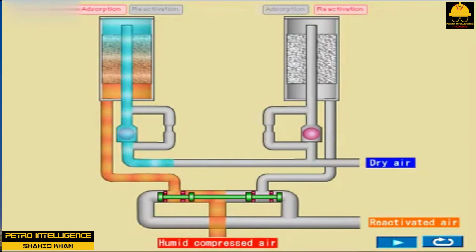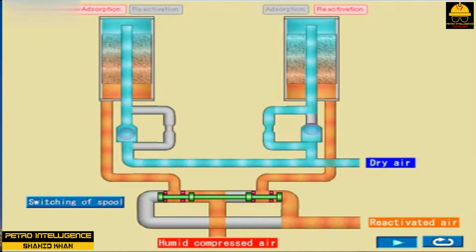In the case of a final product, the quantities are usually so large that special equipment is used to handle it, but the principle is the same. The moisture adhering to the solid is vaporized and carried away by a gas stream because the vapor pressure of the moisture on the solid is lower than that in the gas stream.